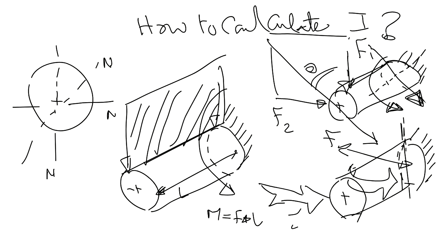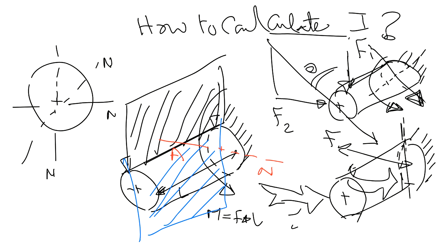As you can see, the plane of your moment is that vertical plane. Then your neutral axis should be perpendicular, passing by the center of the cross section. So this will be my neutral axis for the first case. You got this one? Yes.